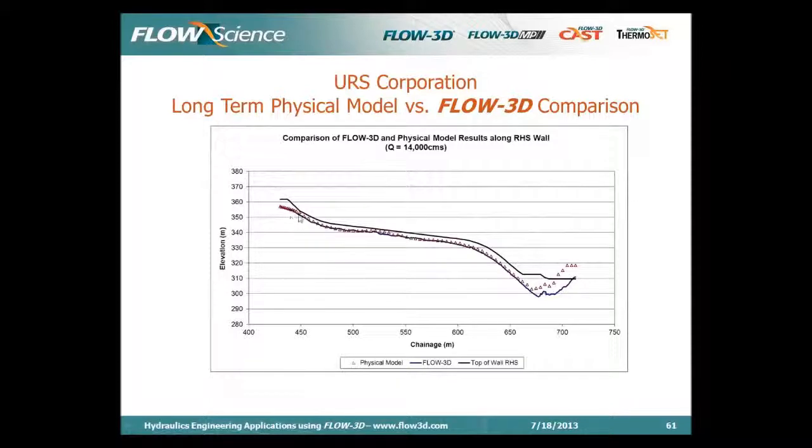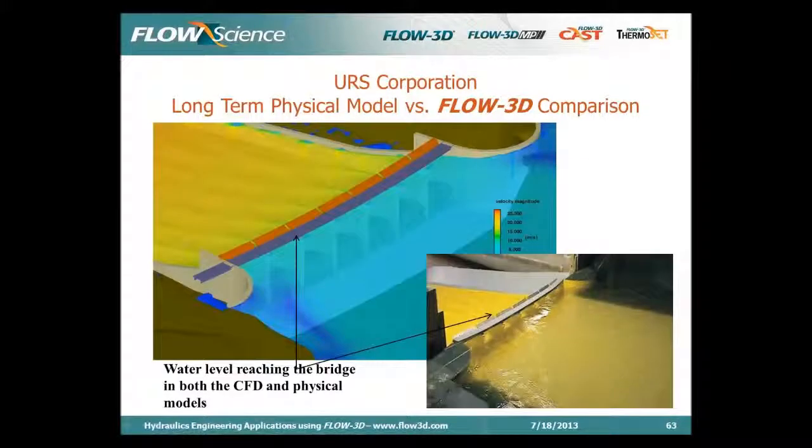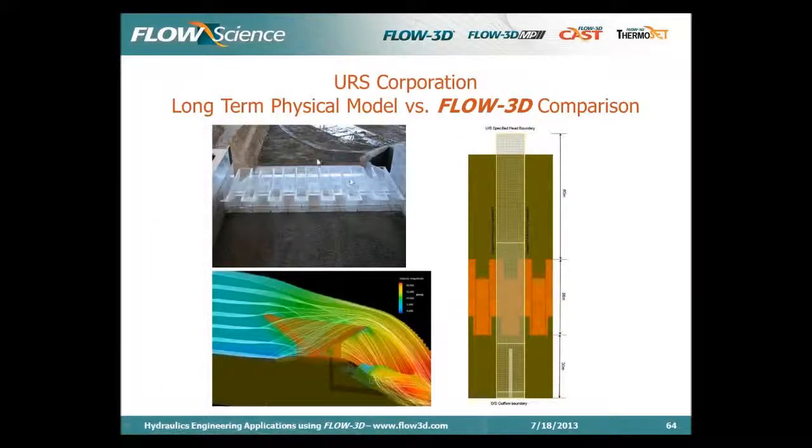What you want to be looking at here is the red dots versus the blue measurements, also very good. And I would just note that I think the discrepancy here has to do with the boundary conditions downstream not being placed far enough downstream. Again, built environments, lab environments, numerical environments. At this point, Flow3D has been validated, even for complex situations, over dozens and dozens of studies.